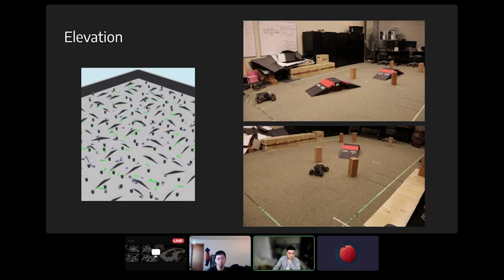Yeah. So, I think for the elevation policy, the rewards are actually the most difficult part about training them. Mostly because sometimes the robots would not want to actually go up a ramp at all to navigate towards the goal. We could have made the simulation environment a little bit less ambiguous, so it would have to traverse ramps. But it was basically a fine balance between these two things, either just going to the goal or going up ramps.